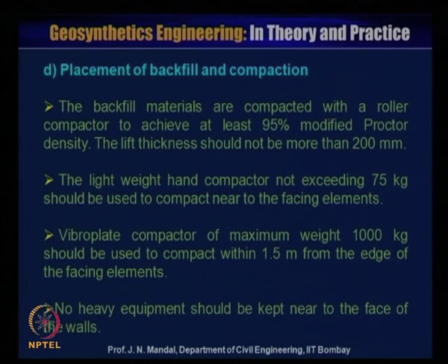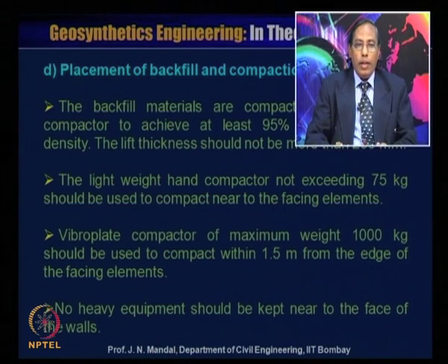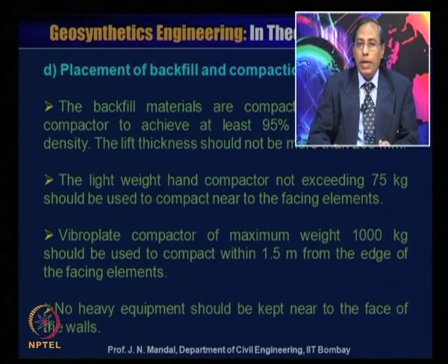This is important because you should properly place the backfill material. Sometimes if you do not properly compact the material and do not properly select the material, there is a possibility for failure. So, the backfill material is compacted with a roller compactor to achieve at least 95% modified Proctor density. The lift thickness should not be more than 200 millimeter. A lightweight hand compactor not exceeding 75 kg should be used to compact near to the facing element.